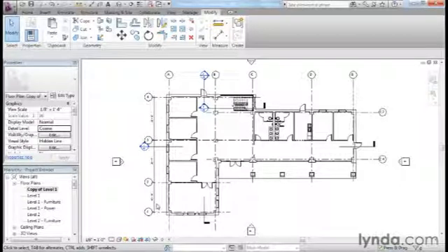Beneath that, we have family. Now, we can have sometimes one family, sometimes many families. A family is an element that has a predefined behavior, structure, or what have you that it shares in common, but that might differ from another similar family. So, for example, a single flush door is a family, but that single flush door might come in a variety of sizes. Those sizes would be the next tier down in the hierarchy called types. Any variations of a family would be saved and defined as types. And then finally, the individual instances that we can click on in the model, those are our instances.